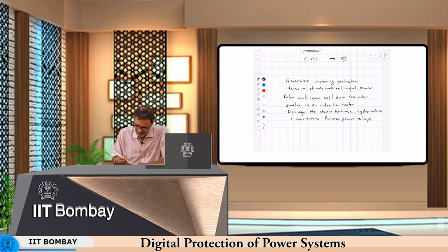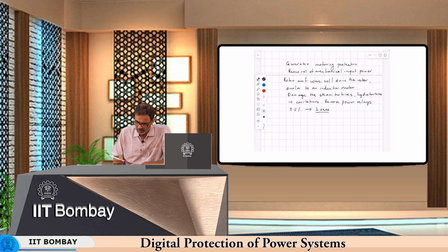The sensitivity is about 0.5%, which it can tolerate, and the time delay is usually of the order of 2 seconds. The next one is over voltage protection. So, this should be fairly straightforward. Over voltage,